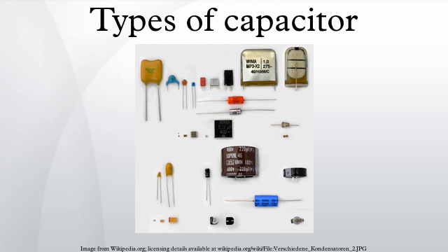IEC standard 62391-1, fixed electric double-layer capacitors for use in electronic equipment, identifies four application classes. Class 1, memory backup, discharge current in mA equals 1 × C.